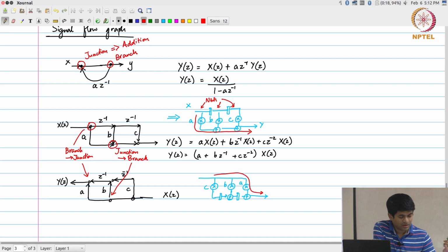So in this case what is happening is the multiplication is happening right here. This is n bits, but this is greater than n bits after the multiplier. So the shifters now need to be bigger or wider. That's one problem.